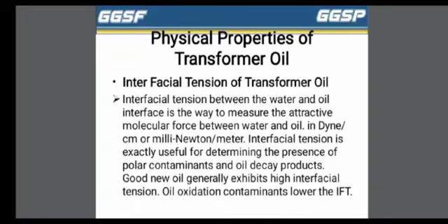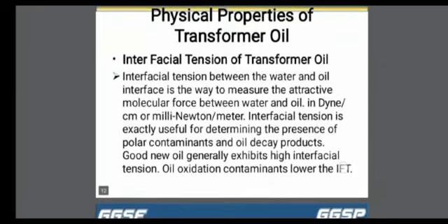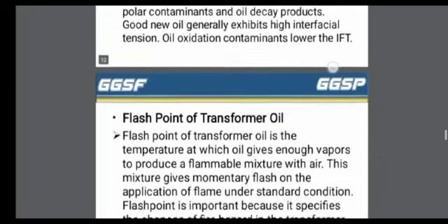Interfacial tension is extremely useful for determining the presence of polar contaminants and oil decay products. Good new oil generally exhibits high interfacial tension. Oil oxidation contaminants lower the IFT.